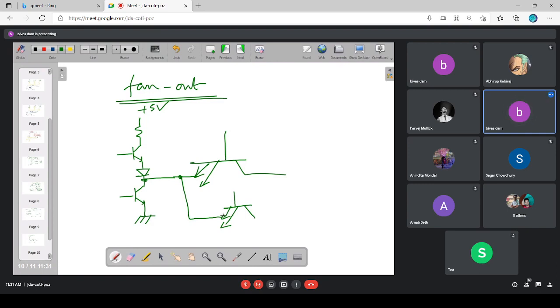It may go to inputs of n different NAND gates. That may also happen. Now the value of n may be 1, 2, 3, 4, 5, 6, anything. That means this output is driving current to here as well as here, or it is sinking current from here as well as here.